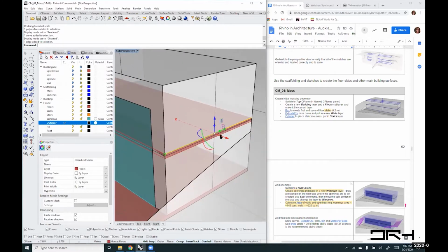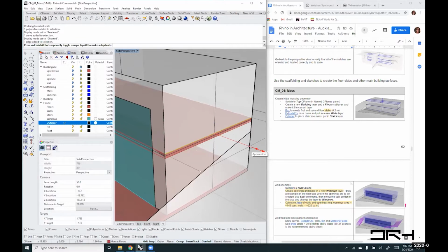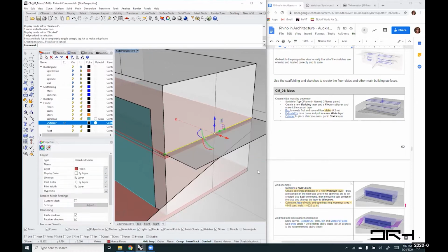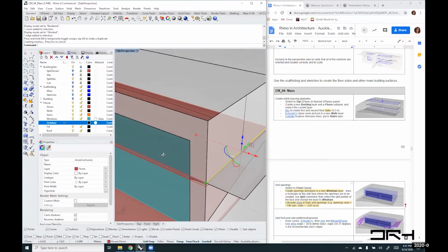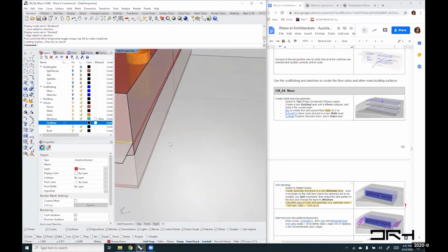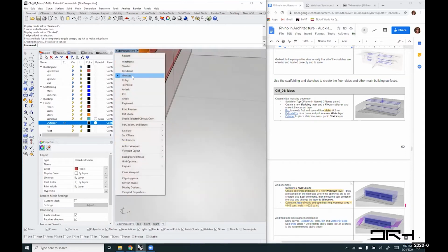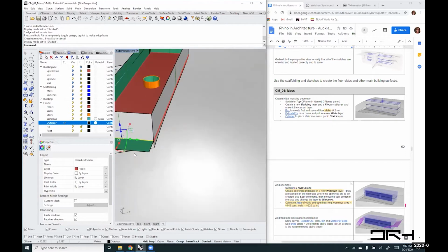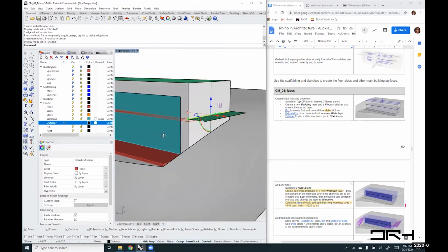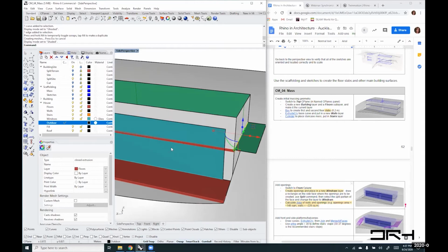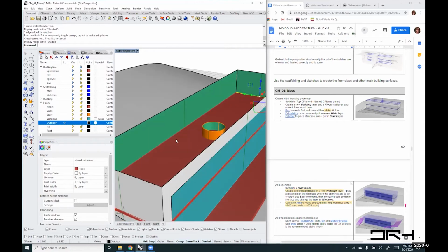Remember, click on that sphere thing. And maybe I just want to extrude out for whichever distance that I'm interested in. Perhaps I want 2 meters, just type 2. And this way you know the distance. Let me just do the shaded mode here, because I just want to see if there is an intersection with the site as well.